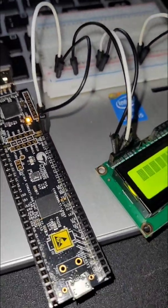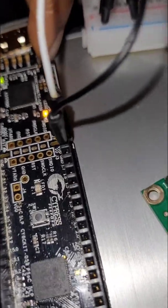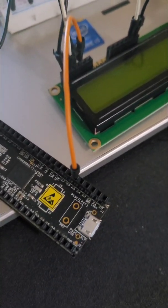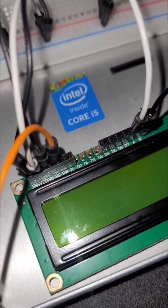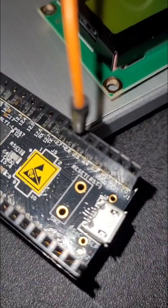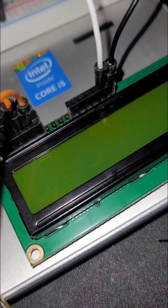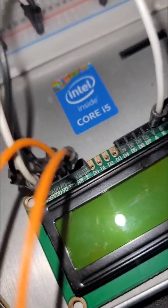So I would like to disconnect my PSoC. The RW pin should go to pin 26. The E pin should go to pin 24.